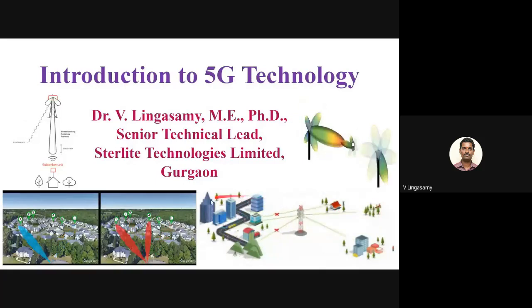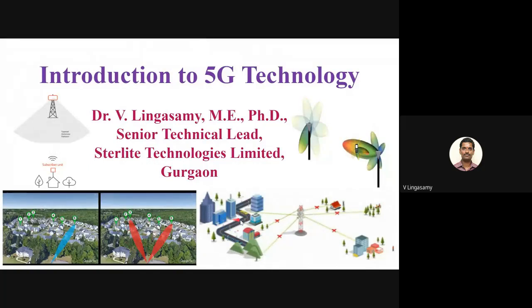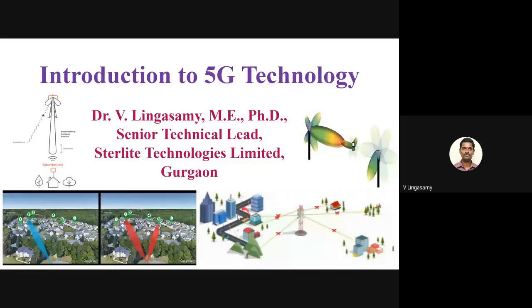Here is the MIMO, and the requirement for it. Why do we require MIMO? Because we need spatial multiplexing, and we have to make use of multipath to communicate. For example, there is a building and a car going behind it gets disconnected. But when you apply MIMO, for example 8-layer or 4-layer MIMO, it makes use of multipaths, so I can communicate with the user behind the building through a reflection. These are some of the technologies in 5G that are driving it.